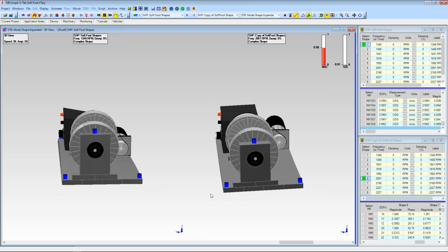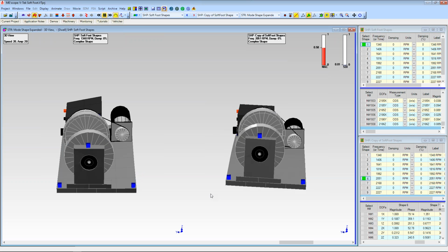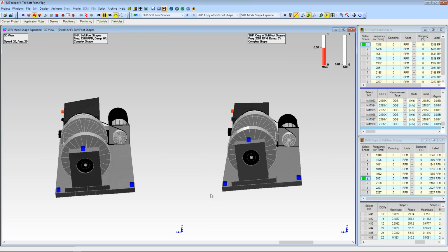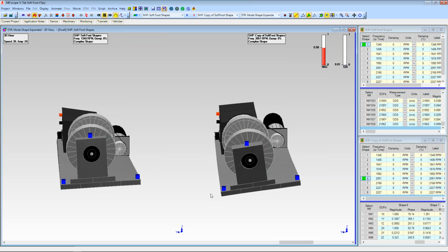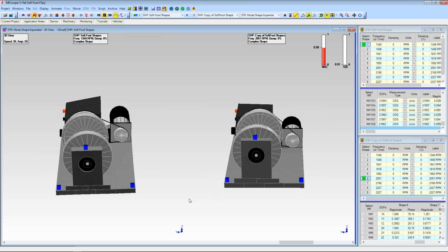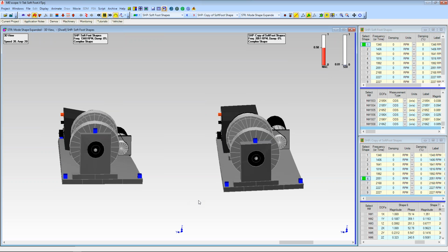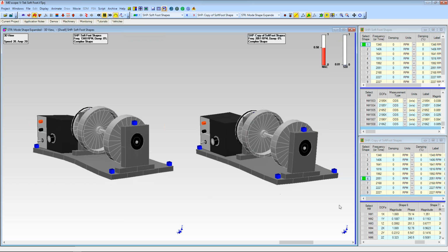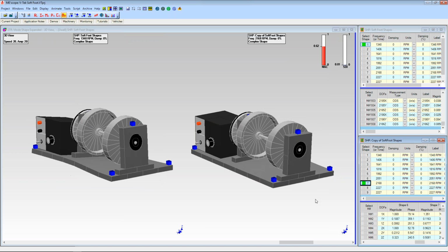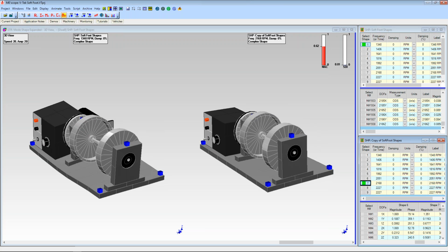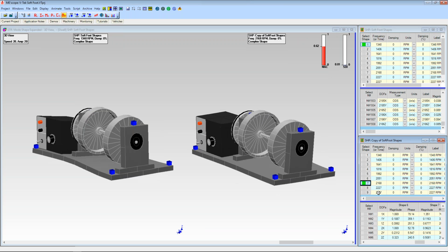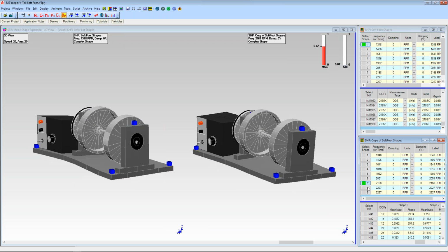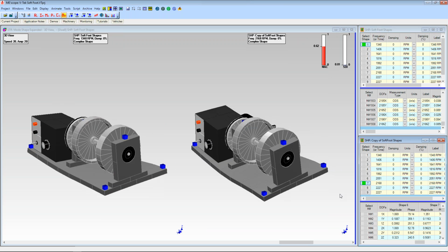So in order to curve fit, to get this to work right, we had to measure what's called a complex participation factor of each mode in the ODS. And then we use those complex numbers to expand the ODS, and we end up with a complex picture like this, which is very much realistic. Now down here we've got several cases of 2000 RPM.